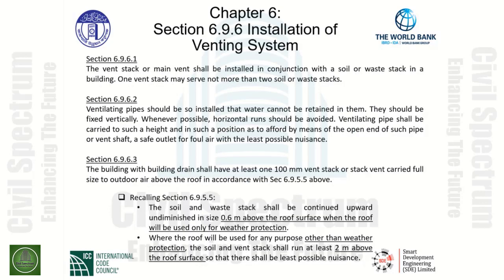Section 6.9.6.1. The vent stack or main vent shall be installed in conjunction with a soil or waste stack in a building. One vent stack may serve not more than 2 soil or waste stacks.